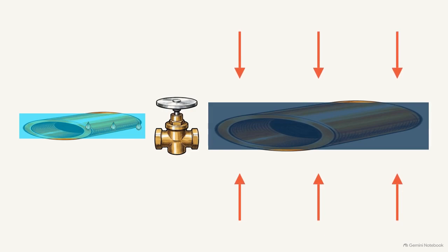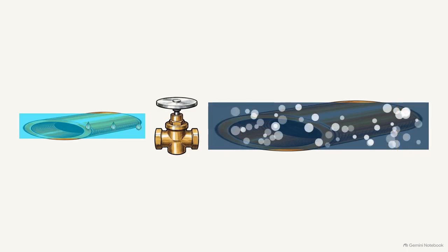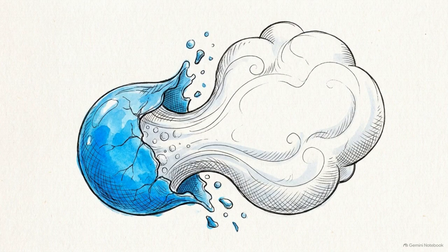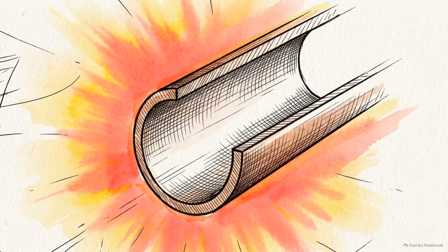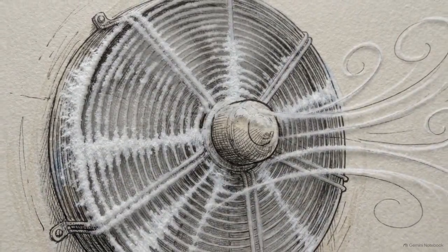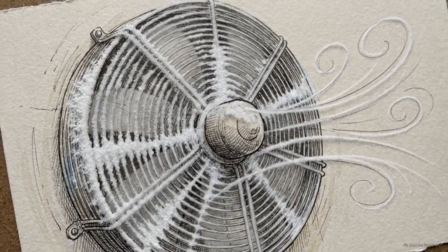Thermodynamics dictate that thermal energy always flows from high temperatures to low temperatures to reach equilibrium. Because the internal fluid is colder, warmer ambient air transfers its thermal energy directly through the copper wall. As this energy enters the liquid, it acts as latent heat, forcing the refrigerant to boil and vaporize. It is during this specific transition from a liquid to a gas that the fluid utilizes latent heat. This phase change is where the vast majority of heat absorption actually occurs. A simple fluctuation in temperature cannot absorb commercial-scale thermal energy. Forced phase change is the only mechanism powerful enough to achieve that.